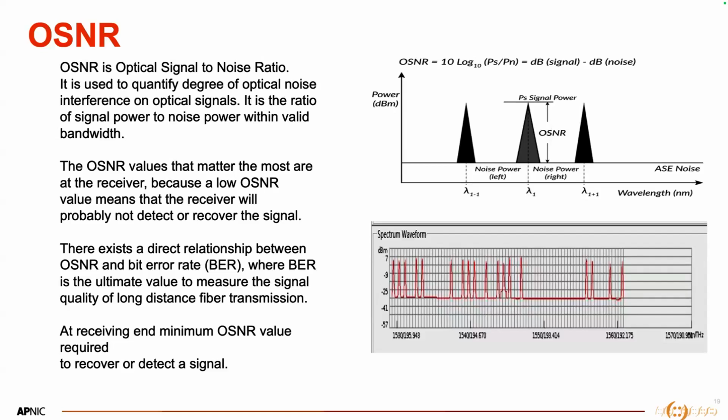So that is why what we usually do is make sure that the TX power of all the lambdas is equal and the same from one single station. Not only a station, basically throughout the whole network, we try to maintain that. That is how you will be able to apply different control or amplification methods in the path throughout the whole network. You understand my point?